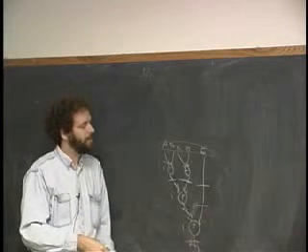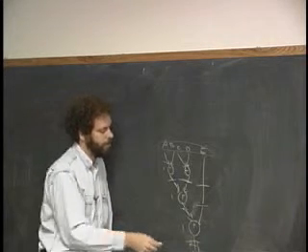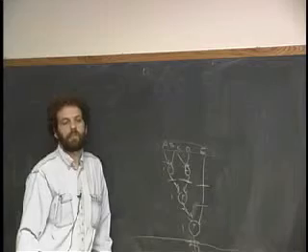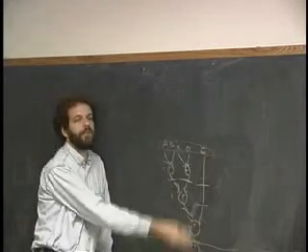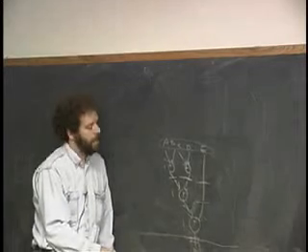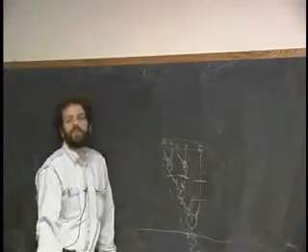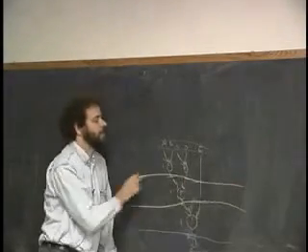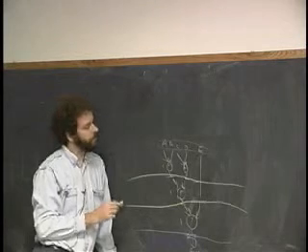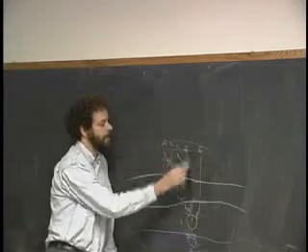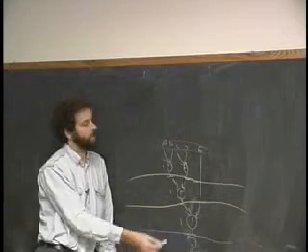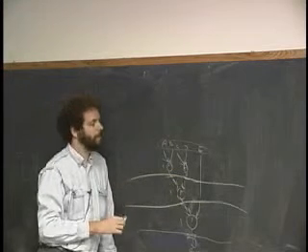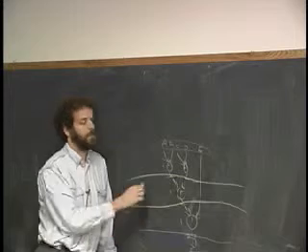Okay, there are several ways to do it, but the easiest way is when you're drawing a pipeline stage, draw it across the entire circuit. First of all, make sure the circuit goes from in to out in a straight line, no looping back or anything like that. And when you draw a pipeline stage, cross all of the wires. So this pipeline stage crosses all of the wires here, and this pipeline stage crosses all the wires here. And thus I guarantee that the number of stages between any input and the output are the same. And that's true everywhere in the circuit. Even if I'm here looking up, the number of stages going up is going to be the same. And so this circuit here is well formed.